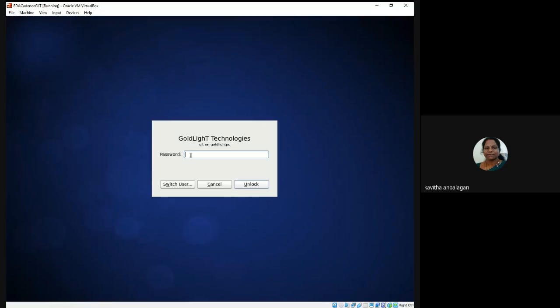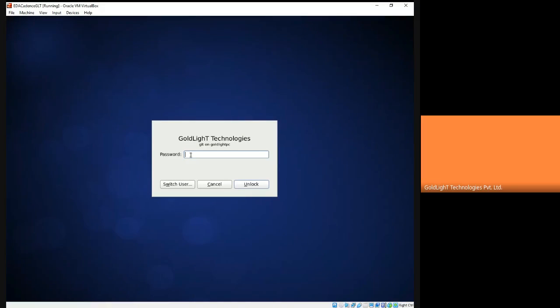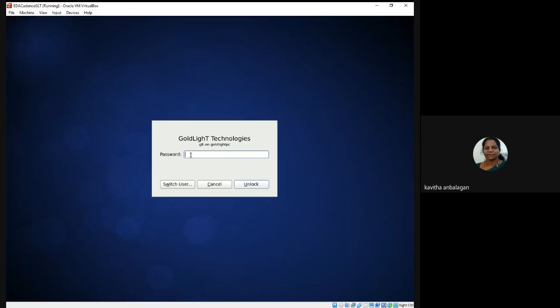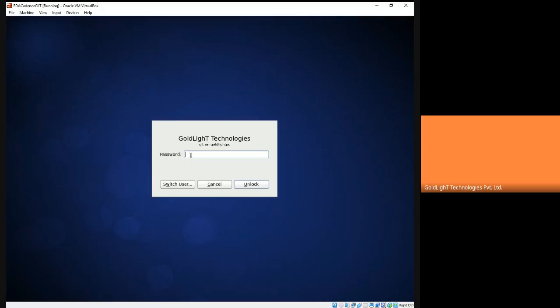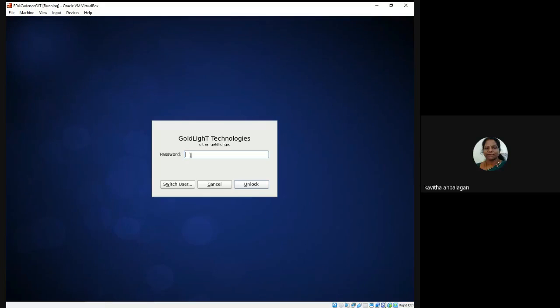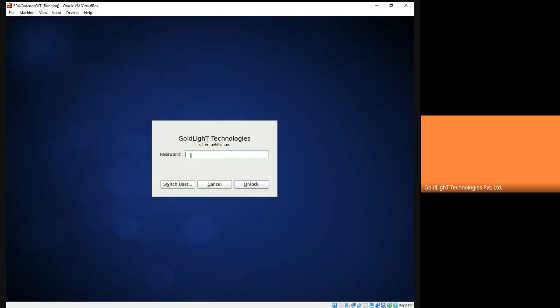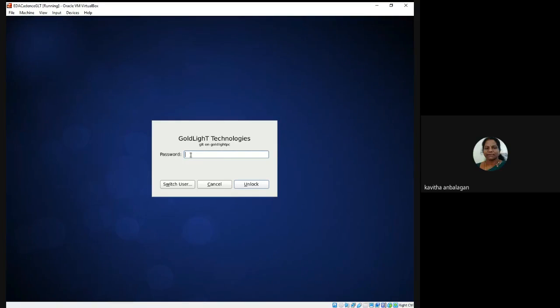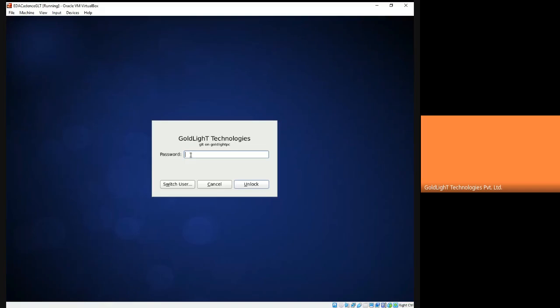Yes, sir. So based on the application, if you are going to make something small like an ADC and a purely back end design, you can use a transistor based design. For that, you can make the design in Cadence Virtuoso. Otherwise you can go with Cadence RTL Compiler and Encounter and all. So that is based on your application. Based on your design, it will measure the power. It is not based on the tool. How we make the algorithm, based on that, it will consume the power.